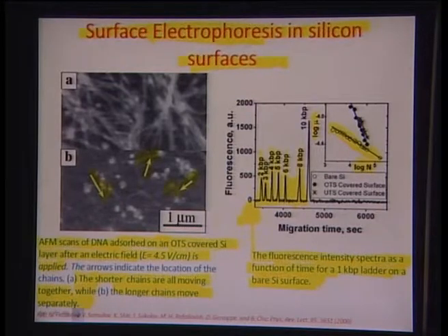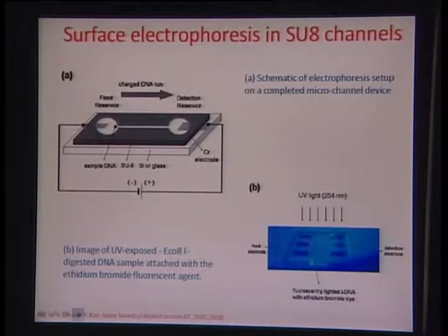Okay, so I'd like to show you how some of the detection can be done, and this is in fact a paper by Kuo et al. at the University of Tokyo. What he talks about is a microfabricated architecture here. You are talking about an SU8 based microchannel with some reservoirs, and this is mounted on top of 2 electrodes which are made up of chromium, on a glass plate, and you connect these electrodes through